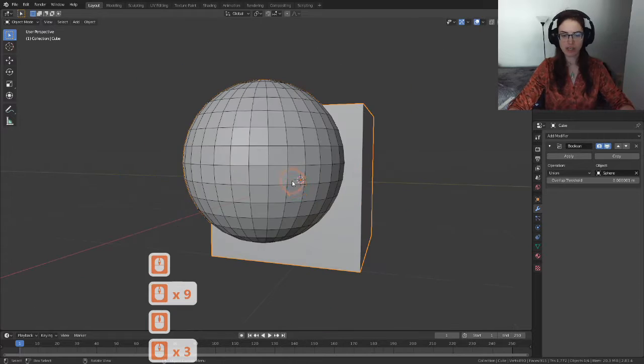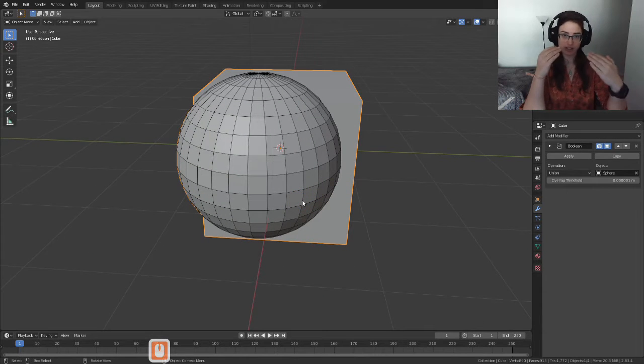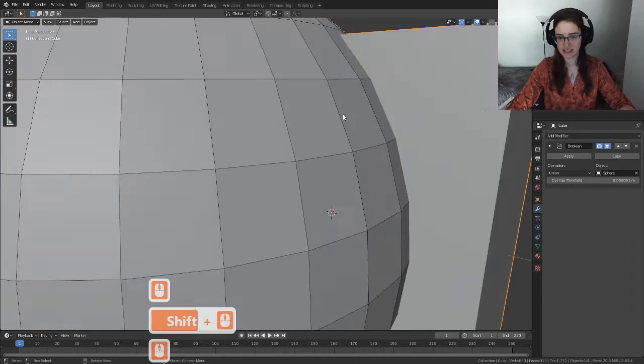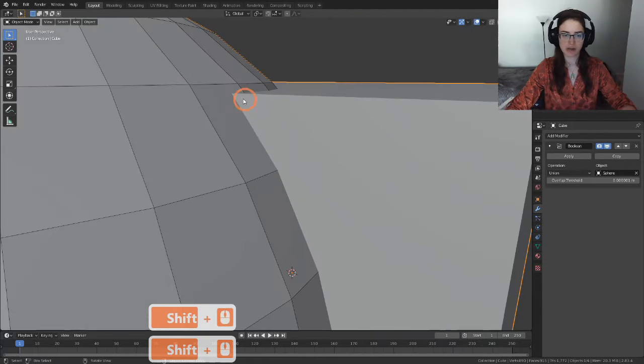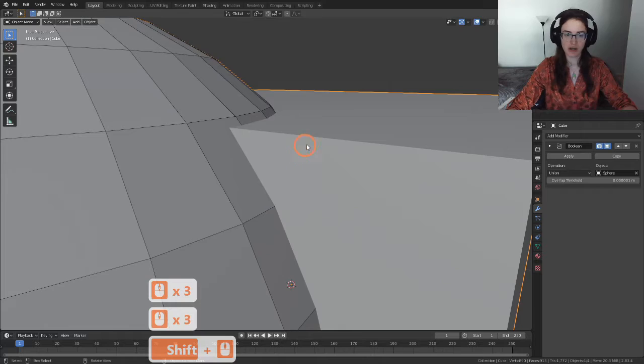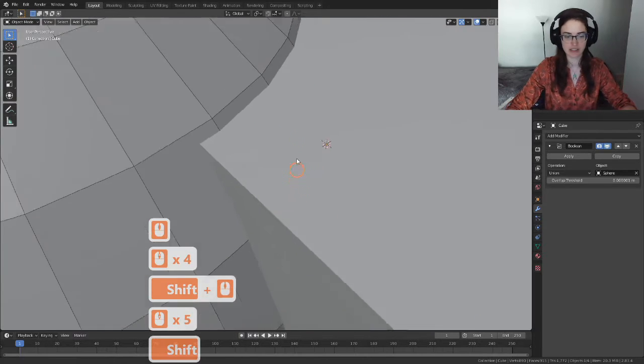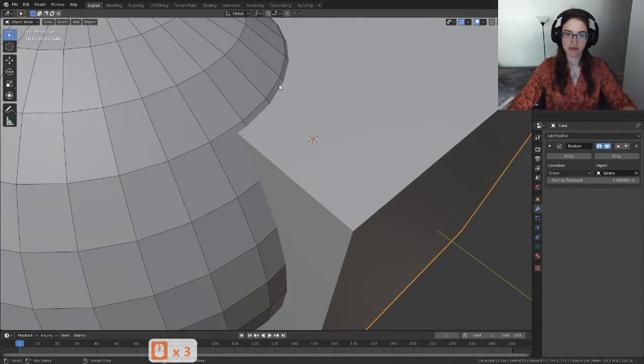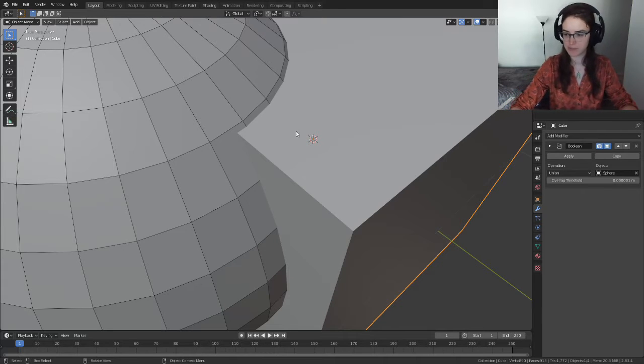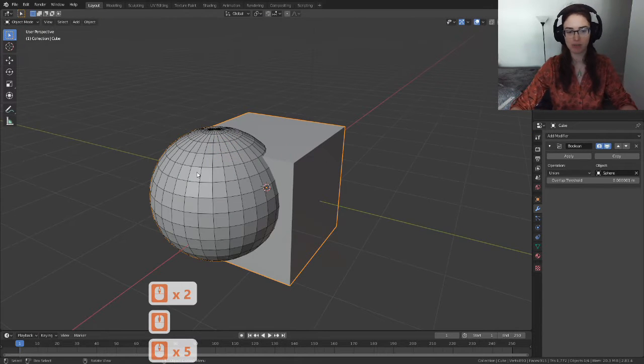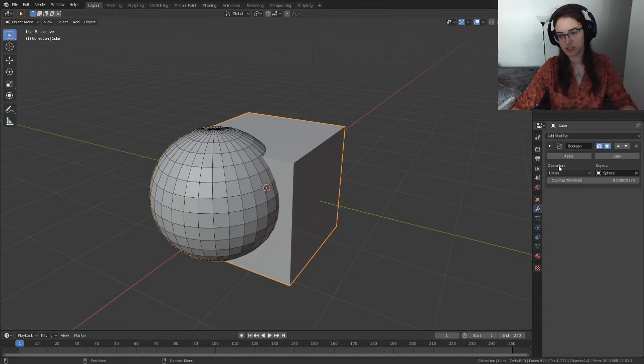So if you, for example, made your frosting for your cupcake, the different levels as two separate objects, you might want to go in with Boolean to combine them and smooth out that edge that merges them. Just for the way that lighting is going to hit this corner, if these were separate objects, it would look a little bit unrealistic compared to if we joined them and wiggled that edge around a little bit. So that's union. So we're combining the sphere to the cube.